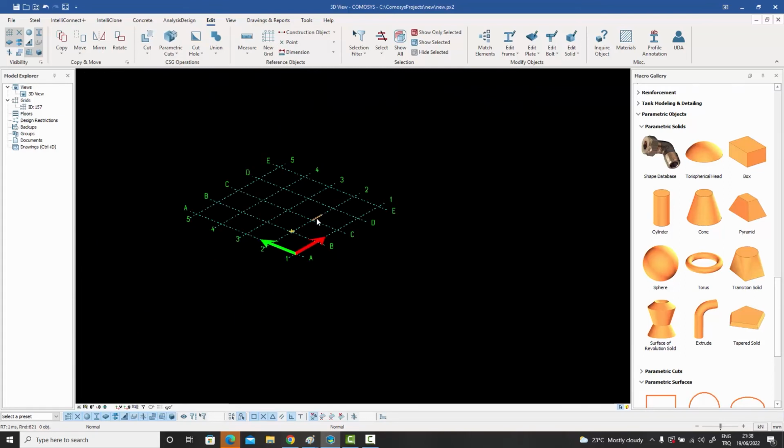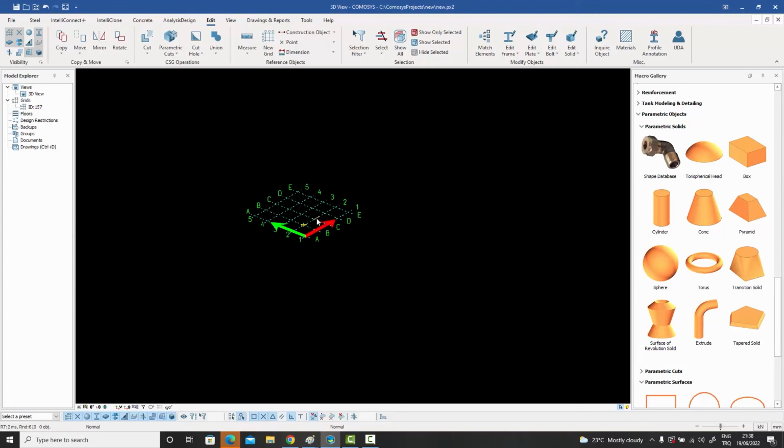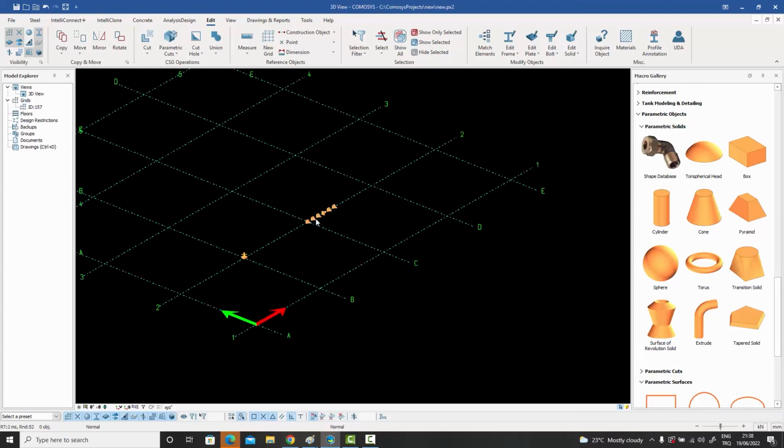Basically, what you have is an option to have 3 or 4 levels of detail which you can define. And what you can eventually define is that when I'm really, really far, I don't even want it to be drawn. Or you can say I want it to be drawn just like a small line, for instance. Or if I'm at this level, I want it to be drawn as a box, for example.